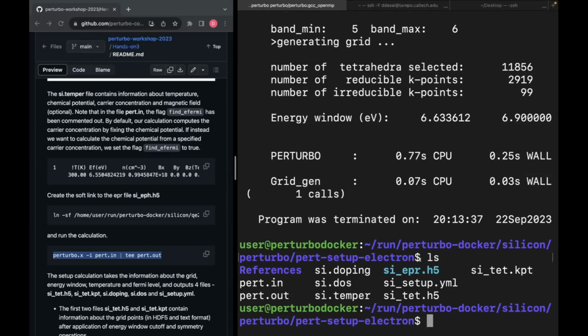And in that you have an assumption that the carrier concentration is fully ionized, right? Yes. But we are neglecting ionized impurities inside our calculation. Because the Fermi level is within the gap, it's okay to just look at the conduction band.